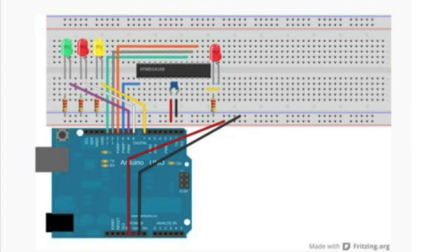The lines you can see that you need are power and ground, which are red and black respectively, and you can see I've run them out to the power rails and then jumpered them over to the AVR. The blue wire is the one that runs to reset. Green runs to system clock, and then gray and orange run to master out and master in respectively. So those 6 are the lines you really need if you'd like to program the chip. The LEDs are just bling.